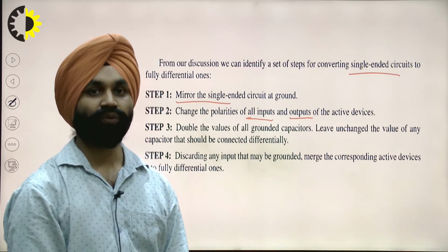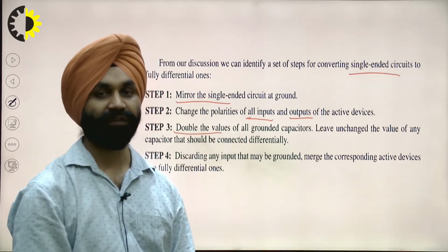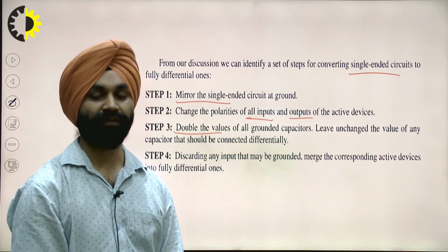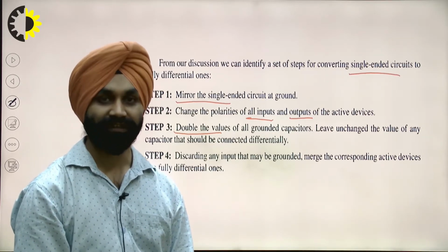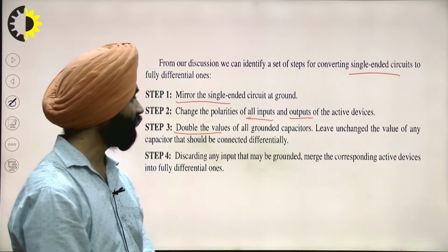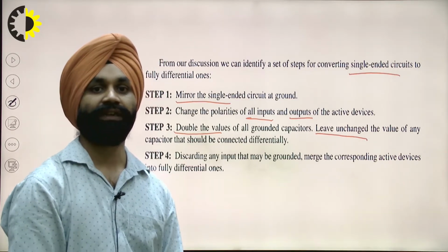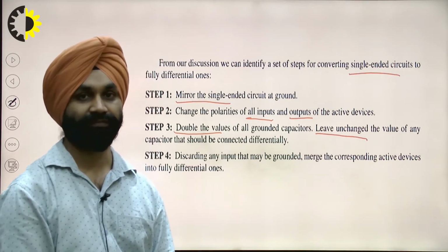Then we take double the values of grounded capacitors, because both the voltages and currents are doubled. We leave unchanged any capacitor that is connected differentially.